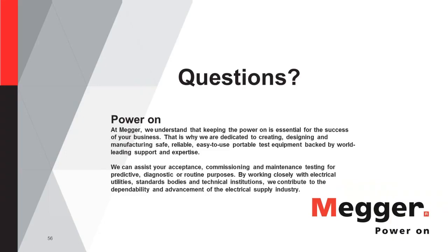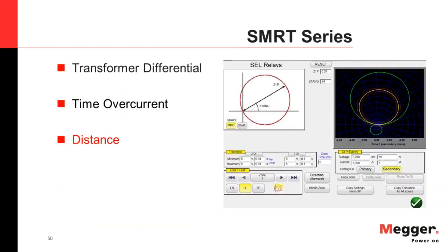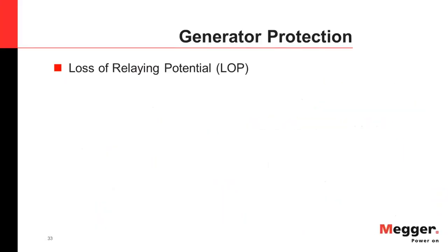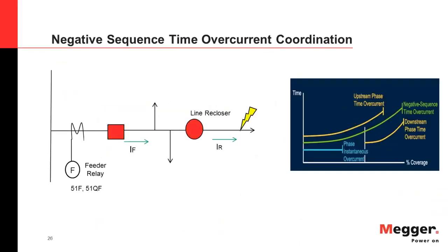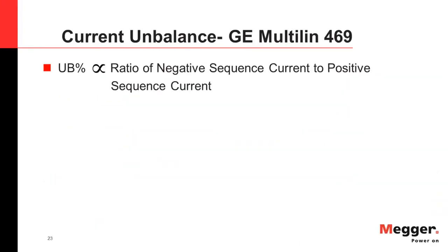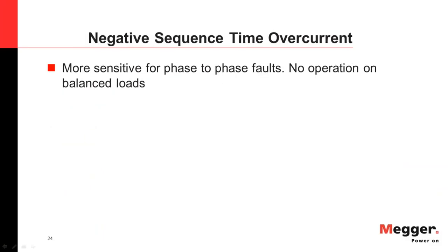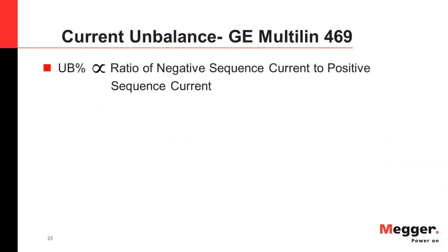But if I have a negative sequence component, I showed in the slide that the negative sequence overcurrent pickup was √3 times the equivalent phase pickup. So you're basically reaching that solution after doing the fault analysis. That equivalent phase pickup is nothing but, let's say, I'm assuming a B to C fault. Can you just go back to the previous slide?